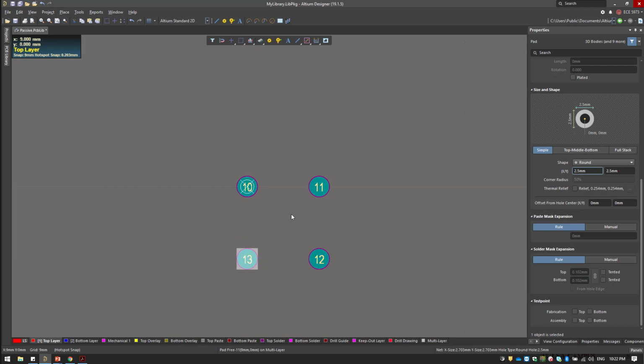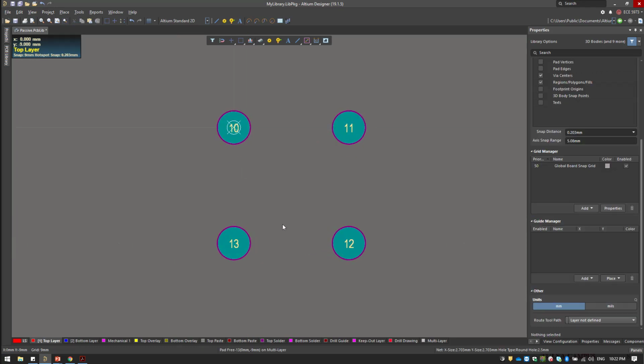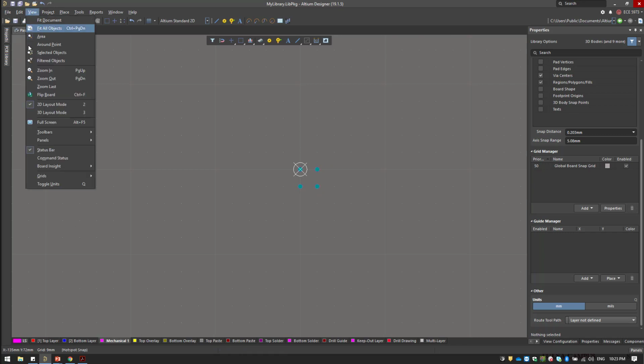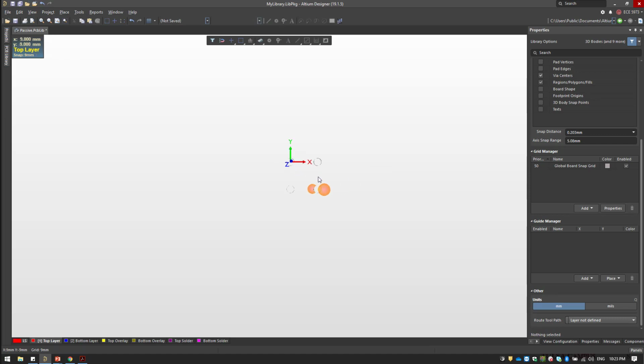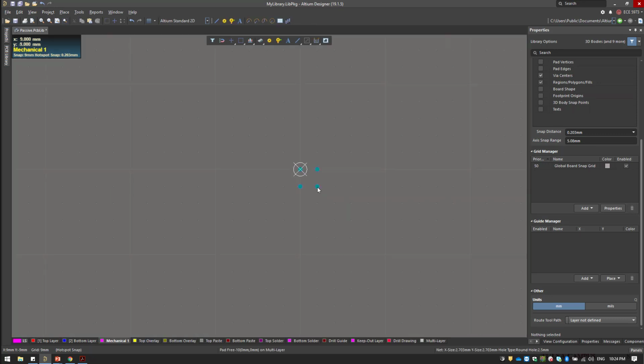and that's it. So if you switch to the 3D model now, it doesn't have a 3D model in here. Okay, so view, yes, it's footprint. Should have 3D model. Okay, here's the 3D model. If you look at it, it's basically just a mechanical hole, nothing else. So we have a problem right now, and the problem is you should not design the holes and the pad to the size of the actual mechanical hole. You need to account for tolerances.